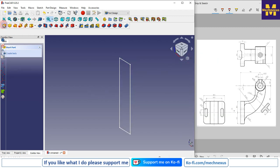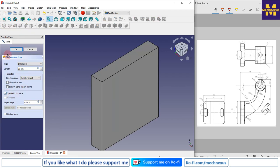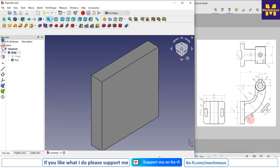Now we will click on Pad and give 80 mm, and in this case making it symmetric to the plane is the most important. So we have made the base feature. Now we will make this profile.